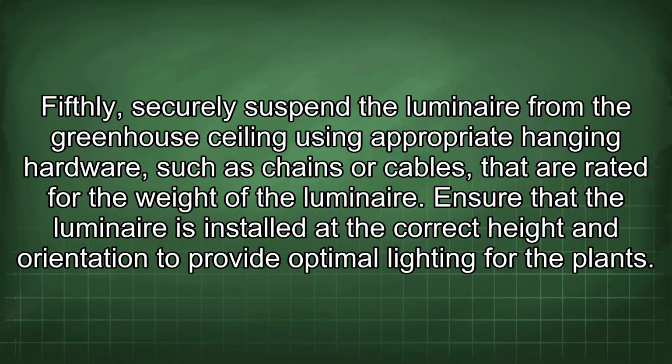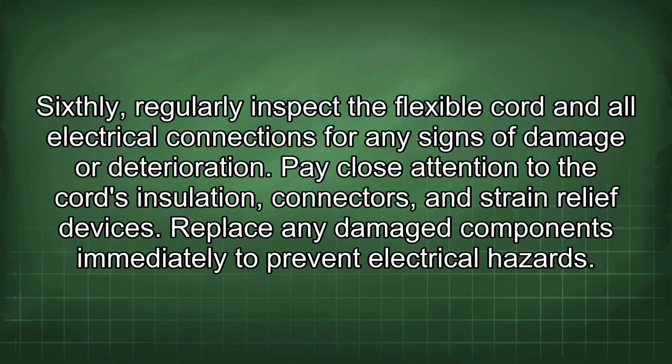Ensure that the luminaire is installed at the correct height and orientation to provide optimal lighting for the plants. Sixthly, regularly inspect the flexible cord and all electrical connections for any signs of damage or deterioration. Pay close attention to the cord's insulation, connectors, and strain relief devices. Replace any damaged components immediately to prevent electrical hazards.